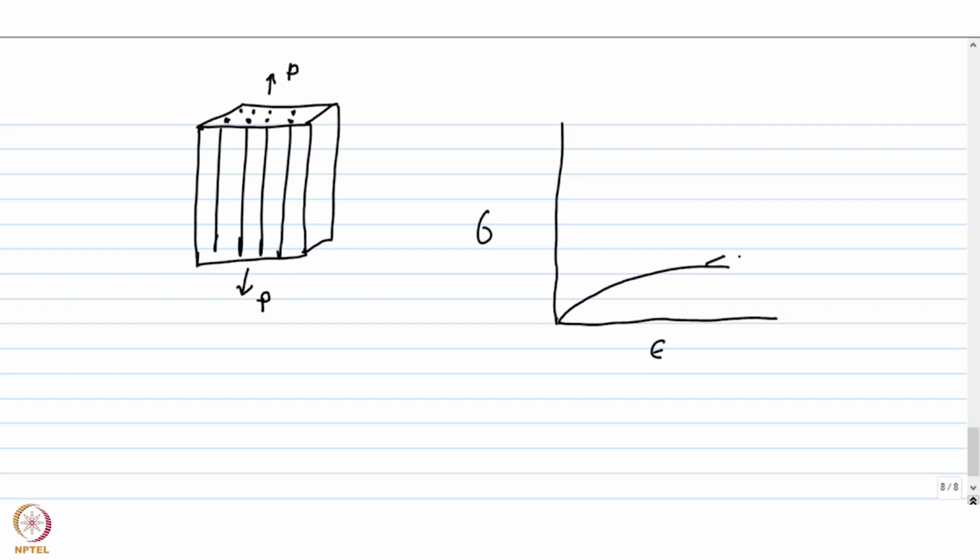So, this is the matrix, which is soft and ductile. Strength is low, but the ductility is high. And if you are talking about a ceramic reinforcement, it is completely the opposite. It is stronger but brittle. There is no plastic deformation at all. Okay, the plastic deformation is almost nil before the fracture.